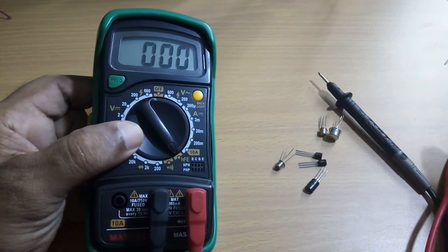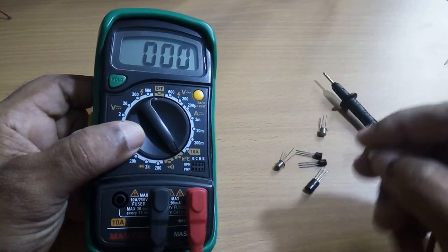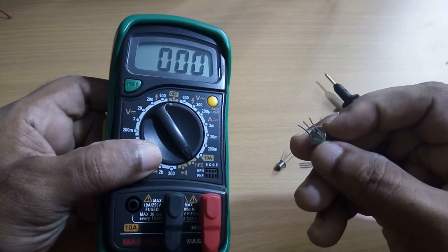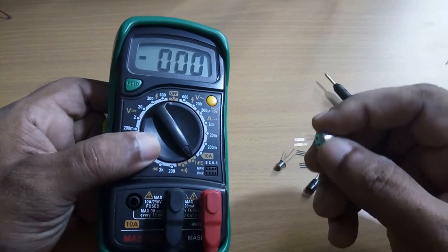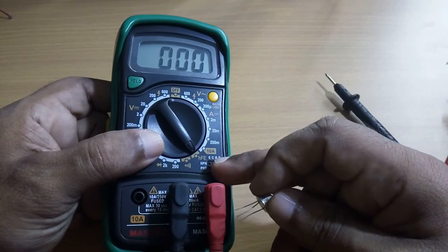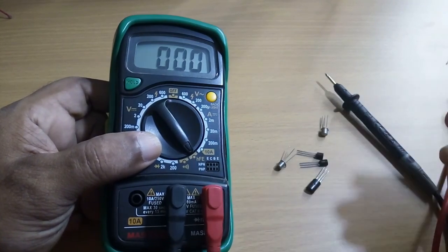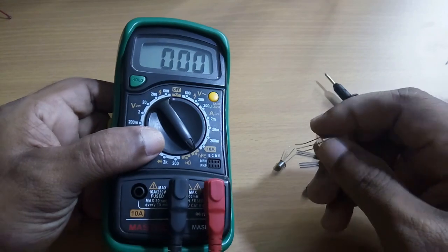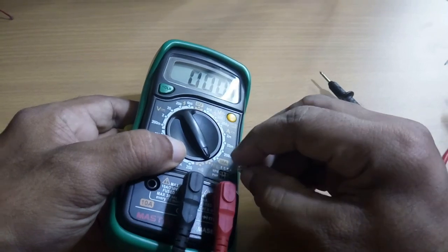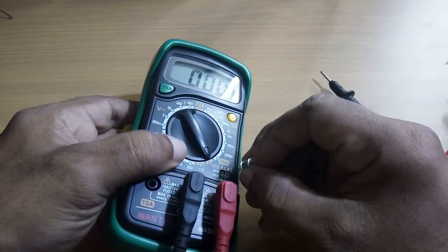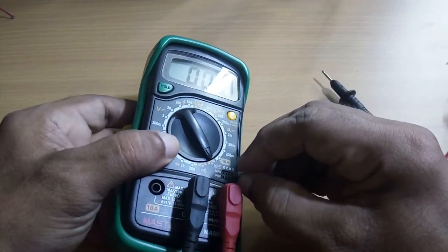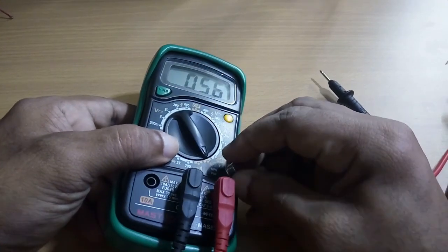We'll have to insert according to that. So first we'll have to understand from the data sheet the type of transistor and the emitter, base and collector terminals. So we'll have to find that out first, and then we'll have to insert the terminals of the transistor into the holes. So here you're just inserting this terminal into the hole, and now you can see the